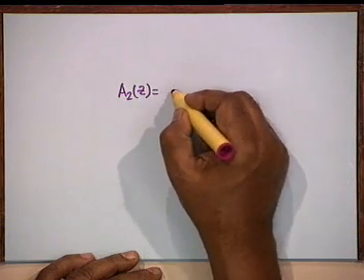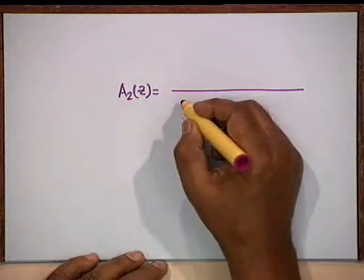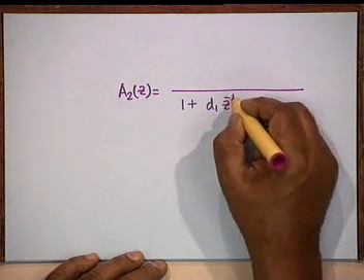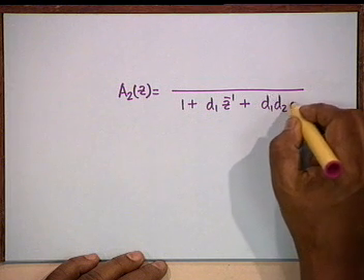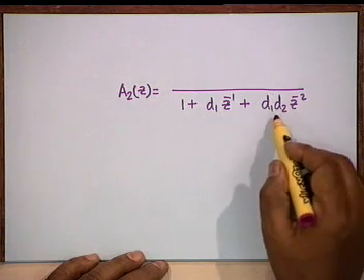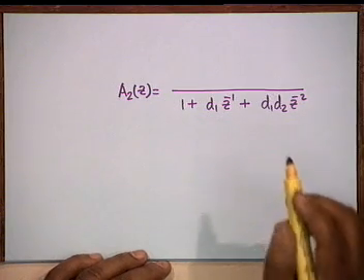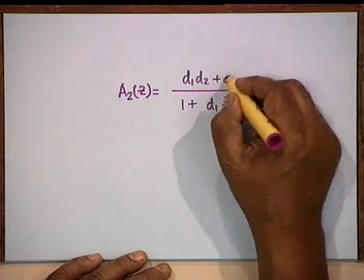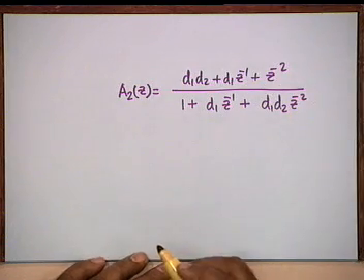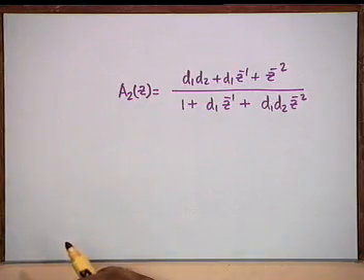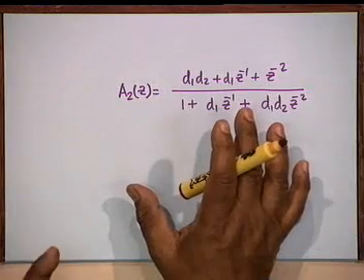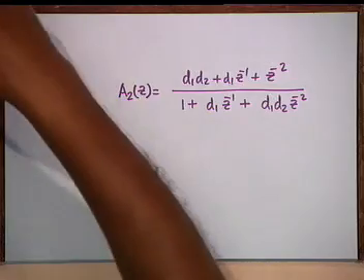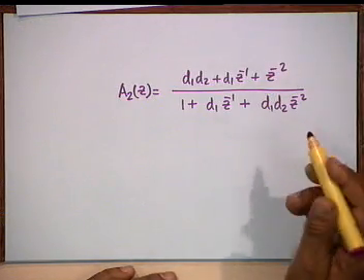Okay. Similarly, if I consider a second order transfer function, I can have of this form 1 plus d1 z inverse plus let us say d1 d2 z to the minus 2. In other words, the coefficient of z to the minus 2 I express as a multiplier of d1. Then my numerator shall be d1 d2 plus d1 z inverse plus z to the minus 2. And if you proceed in exactly similar manner and be lucky, because there are so many choices. Which one shall lead to 2 delays and 2 multipliers, you do not know. This is a second order structure, you require 2 delays and 2 multipliers. And if you choose T11, T22, T21 and T12 properly, you should be able to arrive at this structure.